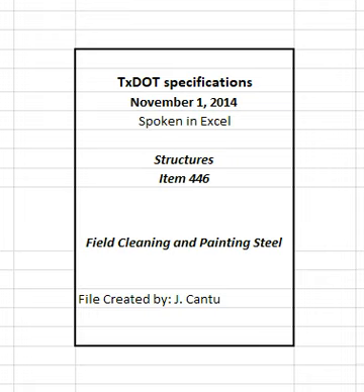Ensure air is clear of dust and remove all blast refuse from cleaned members before the inspector enters the containment to inspect the cleaned surfaces. Remove all blast refuse from the containment before ending work for the day. 4.7.3 Preparation of surfaces. Prepare surfaces before applying paint. 4.7.3.1 General preparation. Clean far enough into any shop-applied paint to ensure removal of all contaminants.